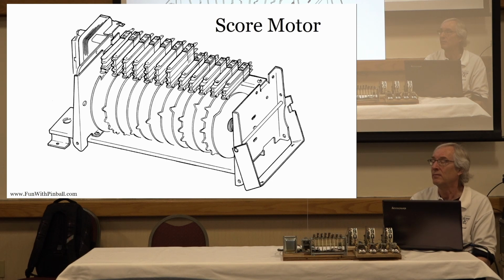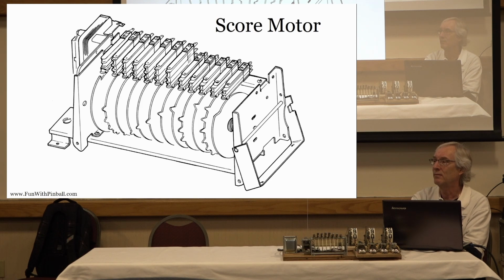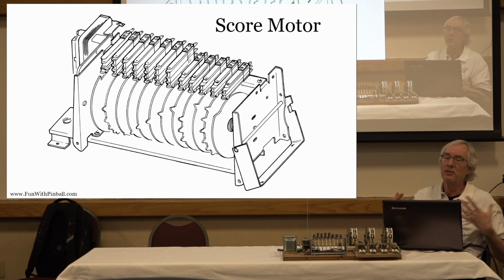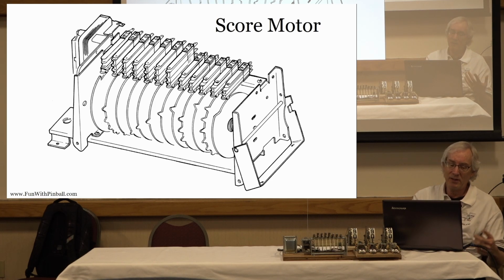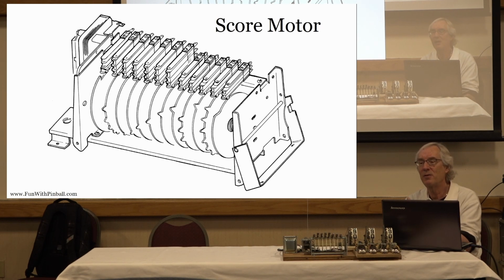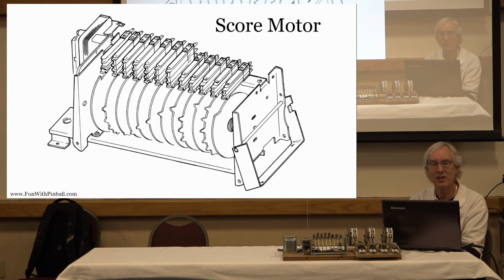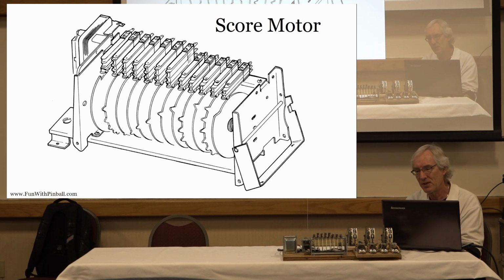How about, since people always ask about it, I'm resetting and it doesn't stop resetting, the reel keeps turning? The score reel or the motor? The score reel and the motor. So the motor making the score reel turn. Right, so the motor, a common complaint: my score motor won't stop turning. And there are a lot of reasons that the score motor turns. It'll turn for 50 points, it'll turn to count a bonus, it's used for all sorts of things.